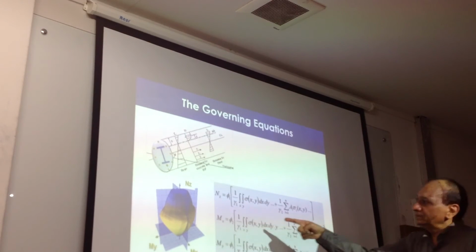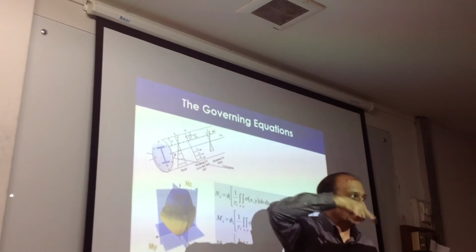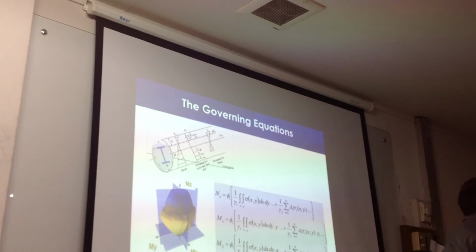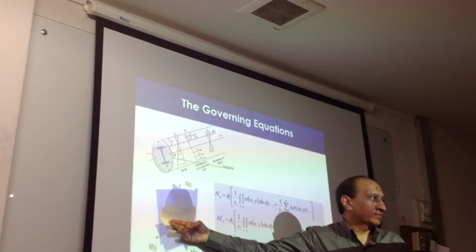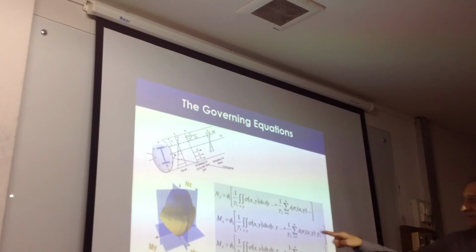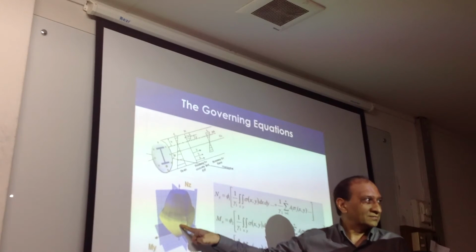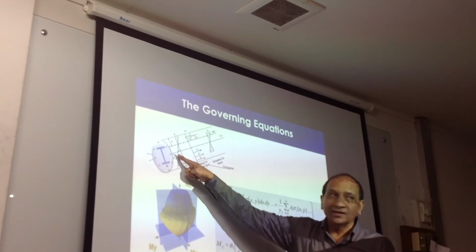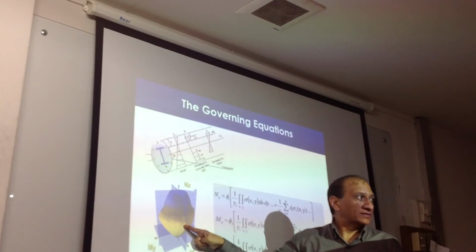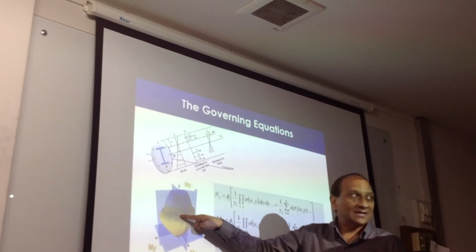So if I calculate all the points by using all of the possible thetas from 0 to 360 and all of the possible values of the strain, I get this surface. Each point will give me one combination of N, Mx, and My, and I'll get one point here. If I change the angle a little bit, I will get another point here. If I change the neutral axis, I will get another point here.